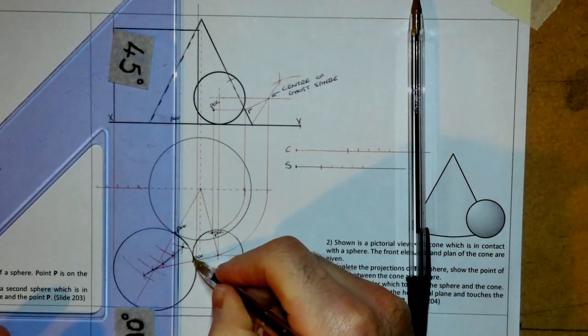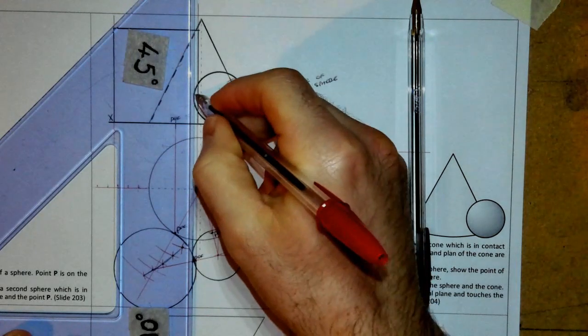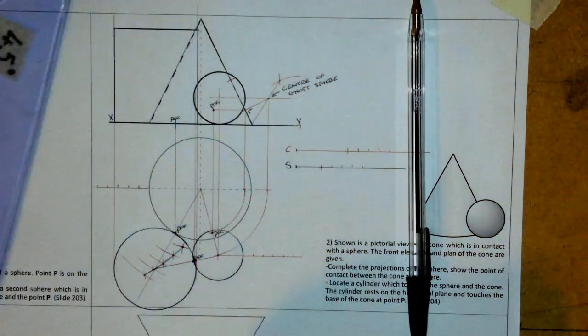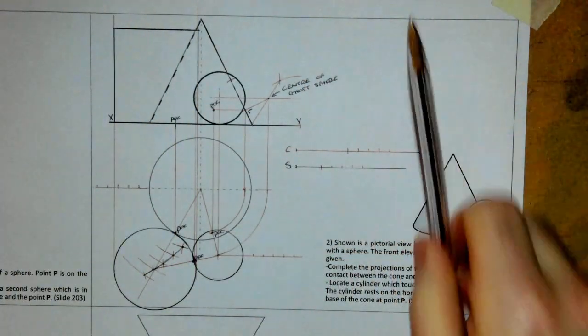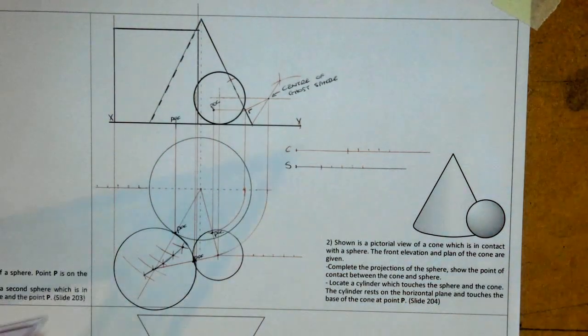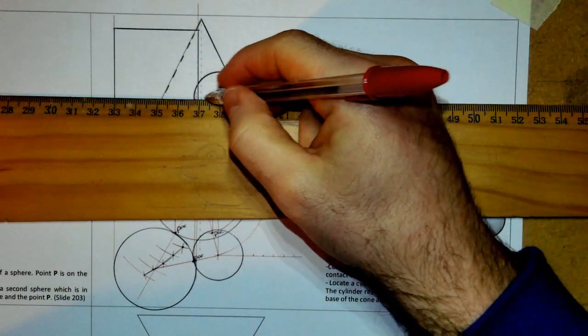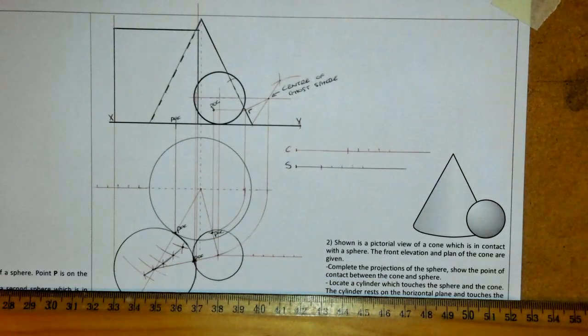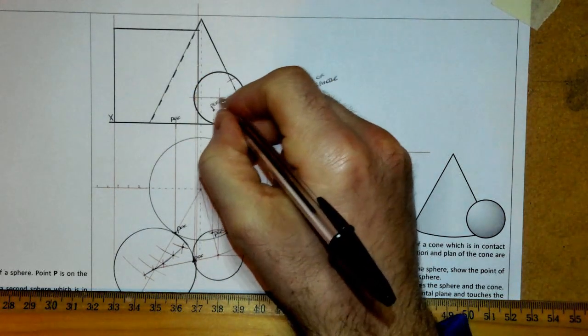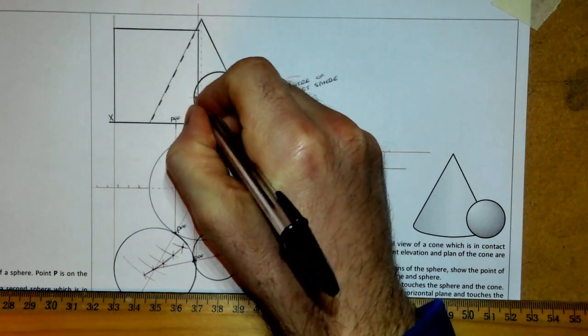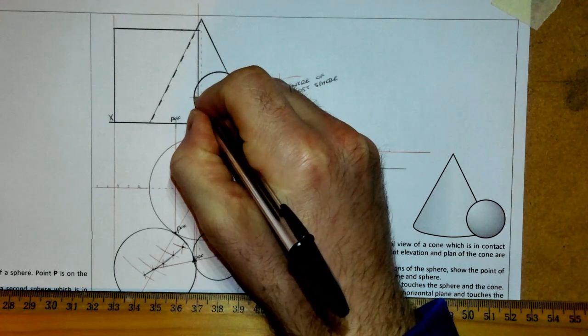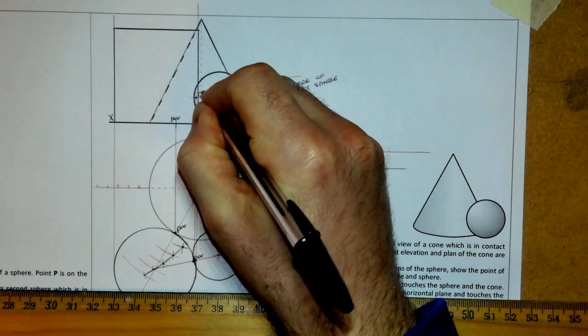So what I would do is I would project that up. It's coming up inside here. And we know a sphere and a cylinder, it's kind of hard to see there now because the lines are getting quite close to each other, but we know a sphere and a cylinder will have their points of contact at the radius height of the sphere. So if we project over the centre of the sphere, right there, that point there is my point of contact.